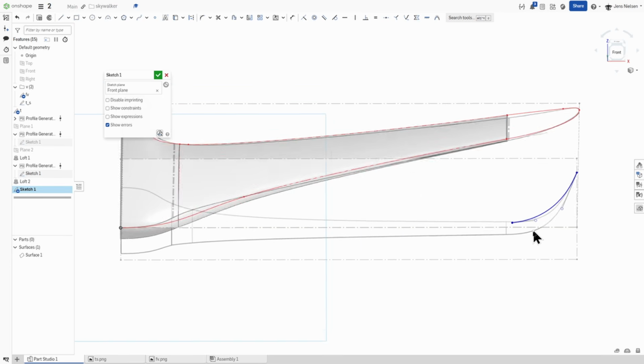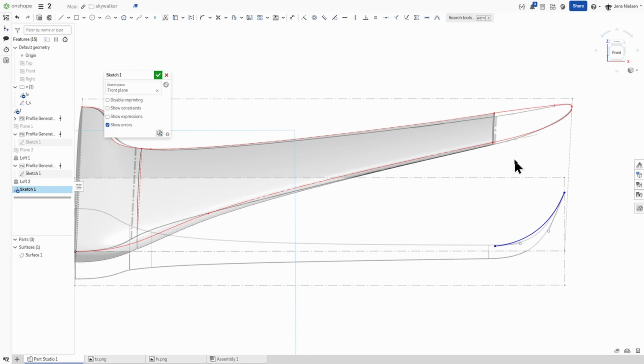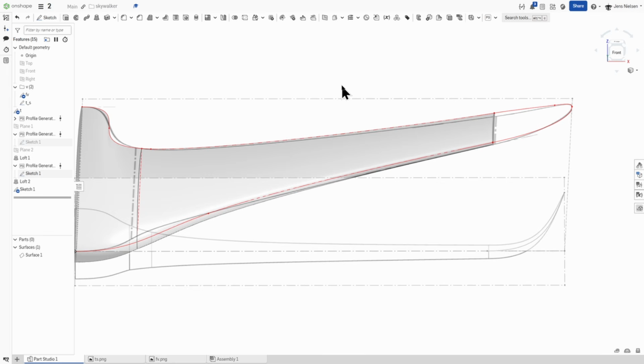and go into a perspective, project that curve here, and make that coincident, and parallel or horizontal constraint here, and maybe pull that out to that position. And exit that sketch.